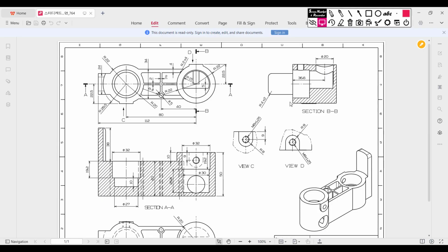So in our drawing, this time we will draw this M8 1.25 extrude cut hole. For that we'll use the hole wizard. It is along the center of the origin of this semicircle profile, and also in view C it is at the origin of the previous circle.